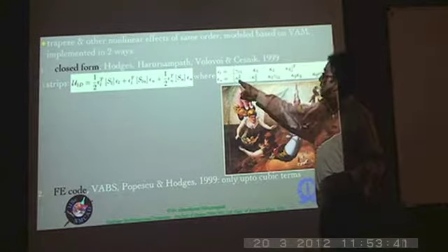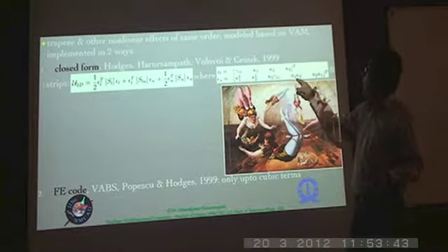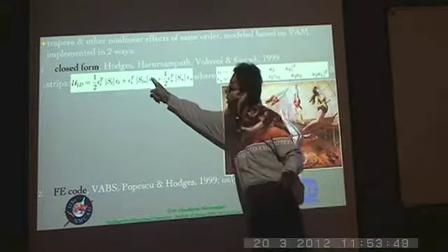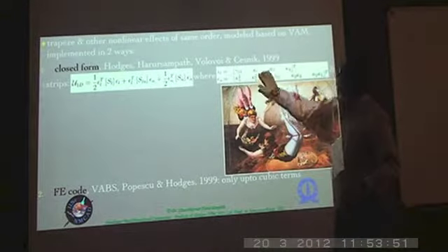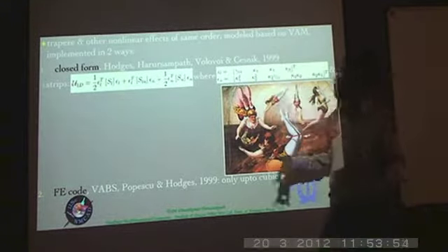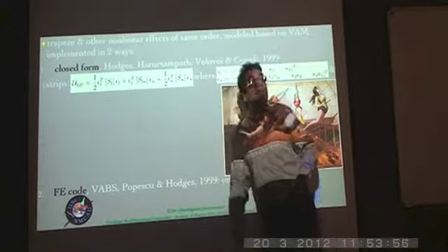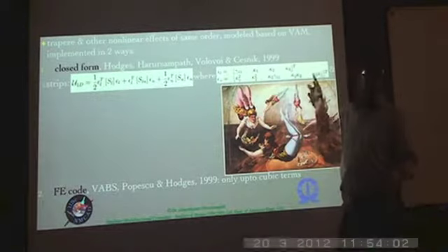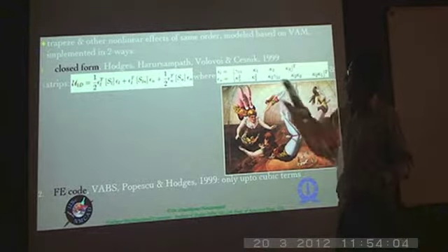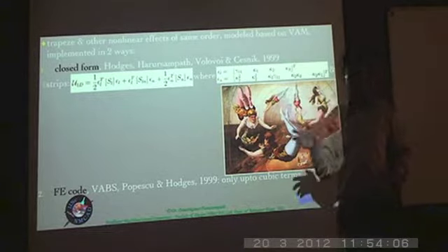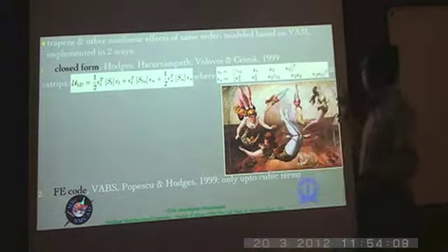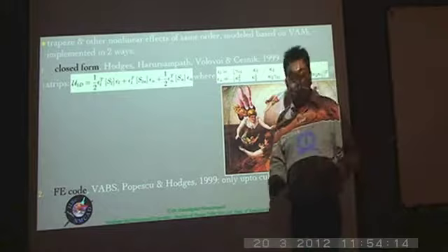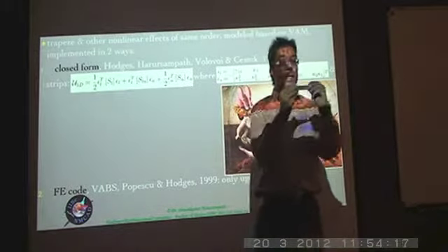So what you have is kappa 1 squared, kappa 2 squared, kappa 2 gamma 11, kappa 2 kappa 3, and kappa 2 kappa 1 as products. And then because it is going to couple with epsilon L, this is going to interact with this, of course, along with a constant coming from the material properties and the geometry. But what is important to see in this epsilon N vector is that all the terms that are there have either a kappa 1 or a kappa 2 or both. So unless kappa 1 and kappa 2 are present, that is, twist per unit length and bending in this particular direction,